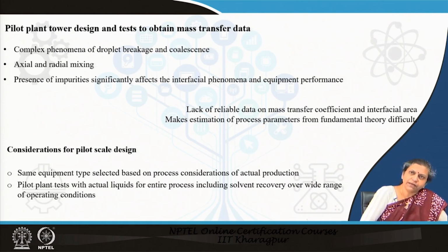Because the extractor involves the complex phenomena of droplet breakage and droplet coalescence, which is not an easily predicted phenomenon. Another thing is there is axial mixing and radial mixing. Then we cannot avoid any sort of impurities, and whenever there are impurities, they significantly affect the interfacial phenomena as well as the equipment performance.